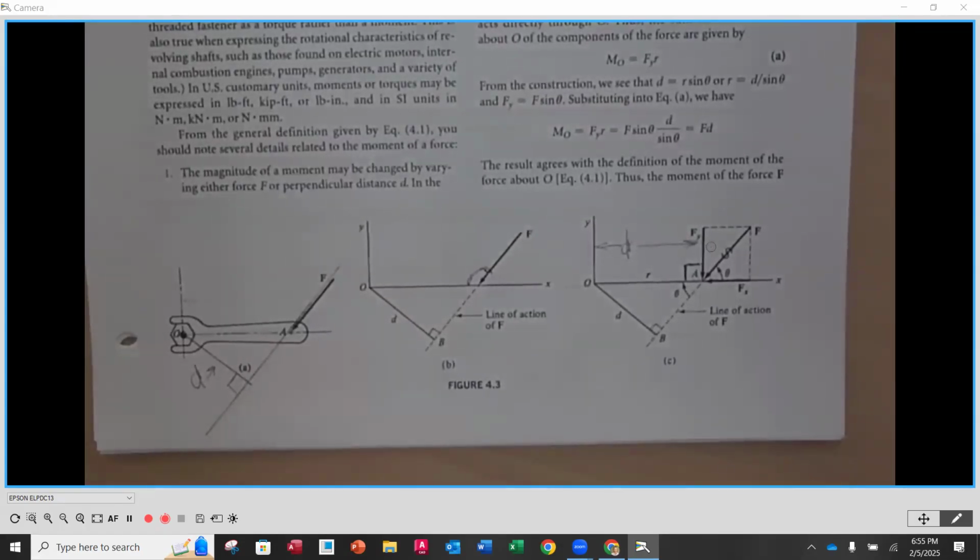In the case of a wrench that's going to tighten a fastener, yes, we talk about the torque rating, or what is the torque going to be? And we say, oh, whatever it is in foot-pounds, right? Or something like that, or in inch-pounds. When we talk about moments, moments are going to be rotations that are created from offset points or axes for items that aren't intended to rotate.